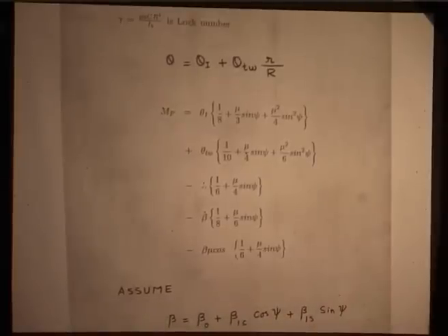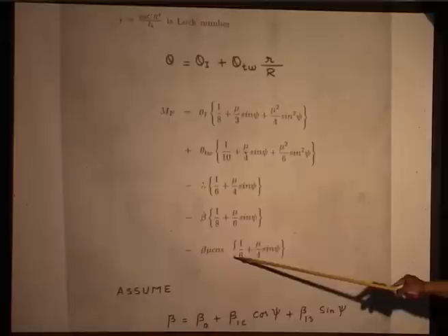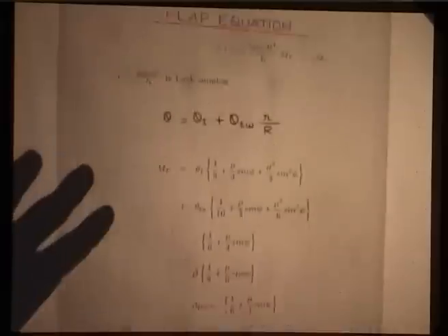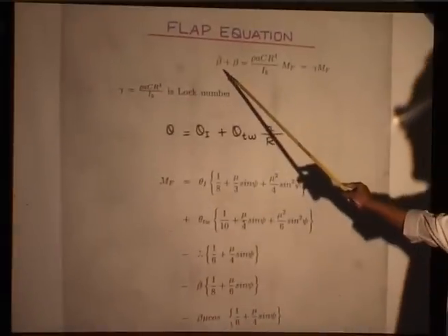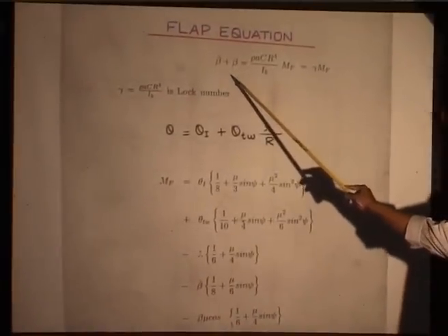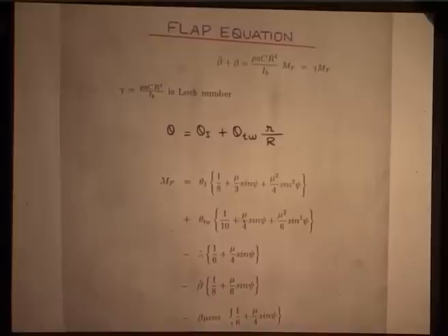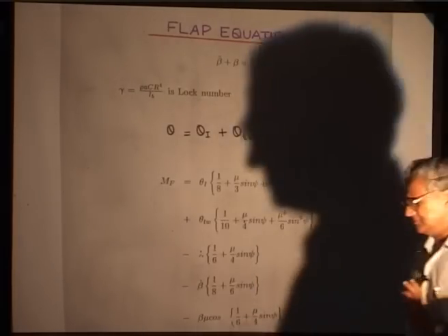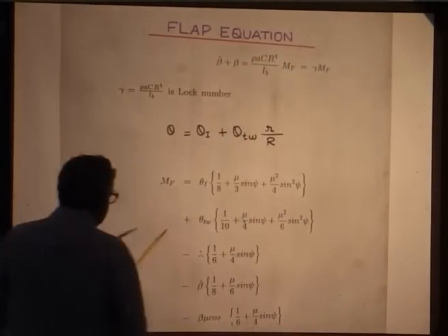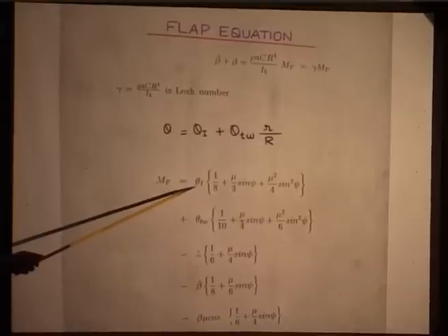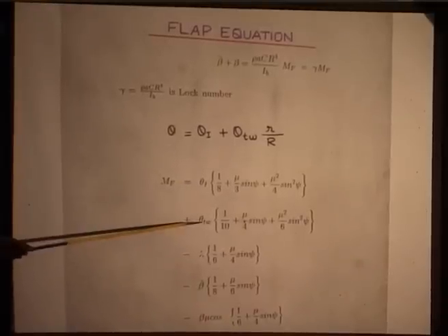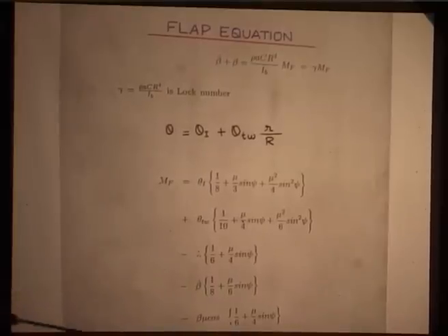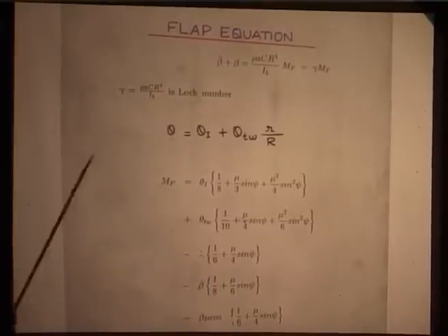Okay? Now if you take these two terms to the left hand side, you will have an inertia, a time derivative term, and you will have a spring term. And then the rest of the quantities are direct inputs, and twist. Blade twist, if it is there, otherwise it is 0, and your inflow, whatever constant you have, that is the constant you can have.